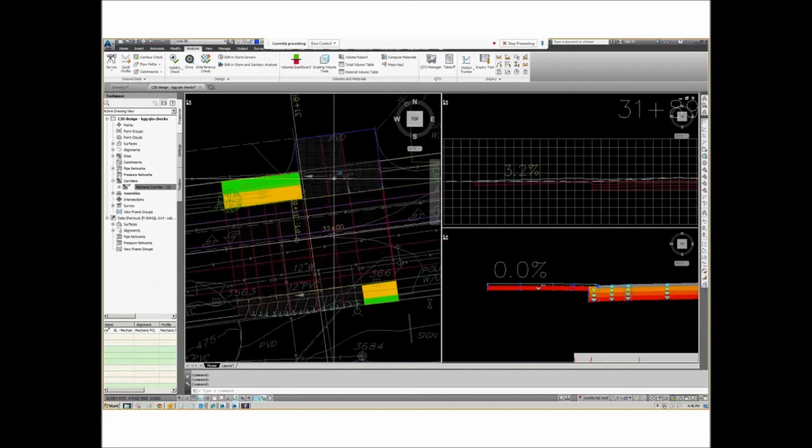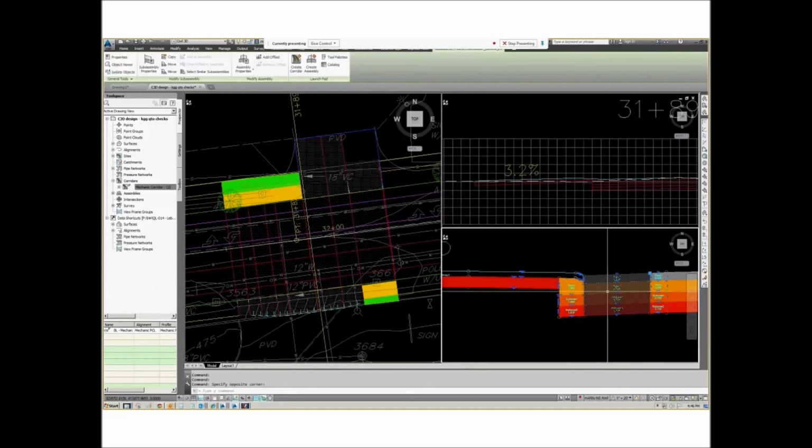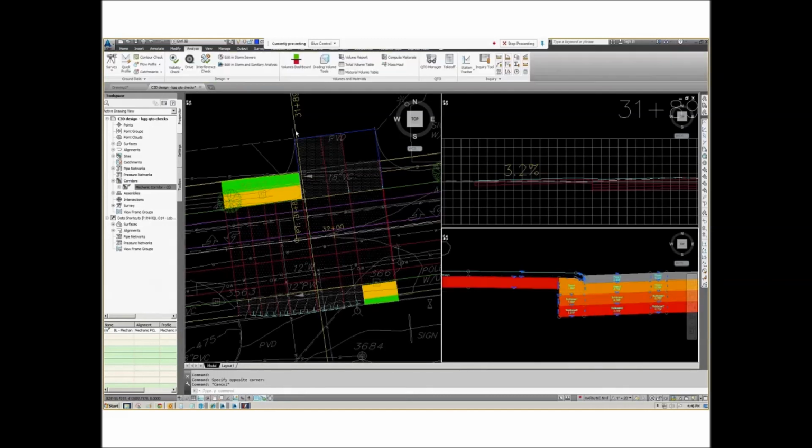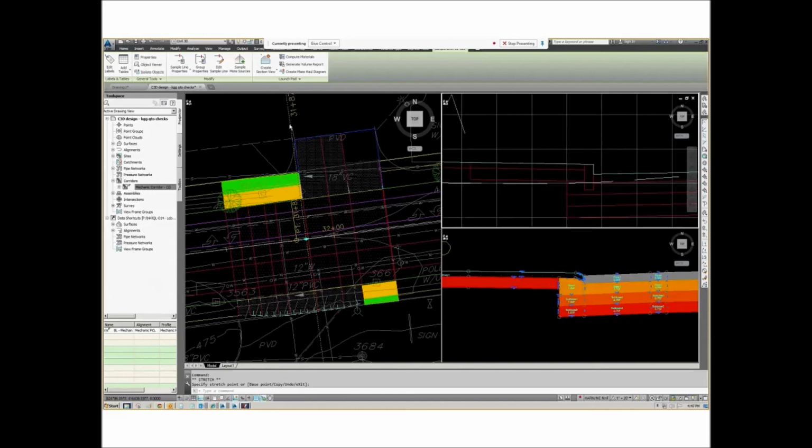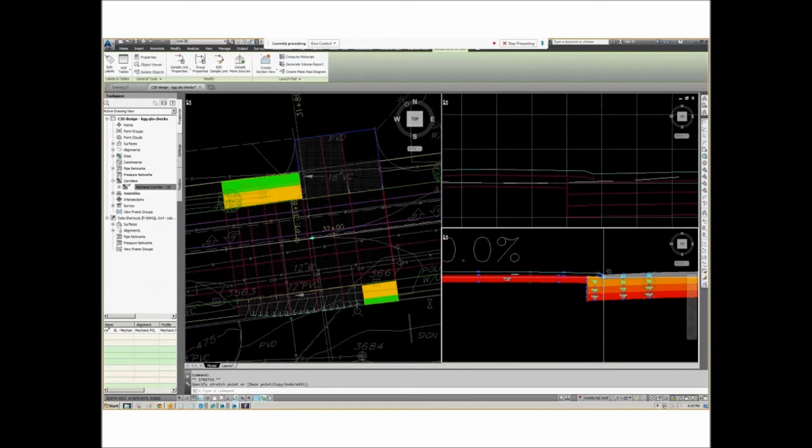So in summary, got this great subassembly, these two subassemblies, one that can be curbed and used in an assembly for the areas just in advance and after the driveways, and then that same gutter line assembly you can shut the curb off and in this case be used as part of a driveway assembly.